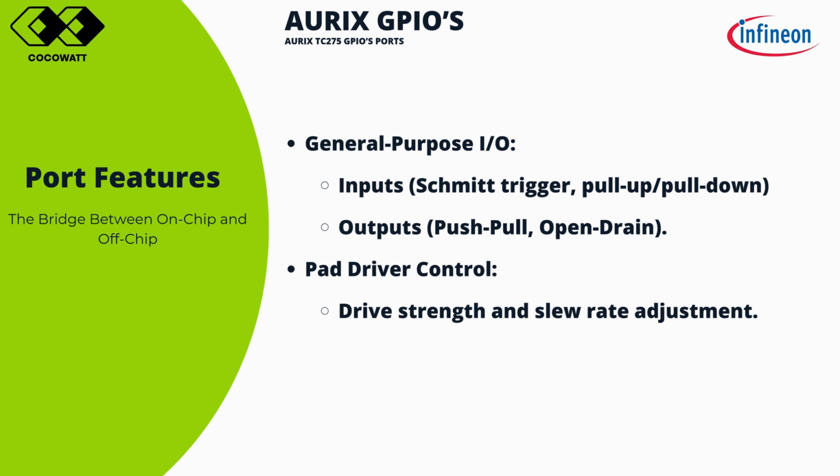Pull-up and pull-down resistors ensure a known logic level when the pin is not connected. High impedance state leaves the pin in an open circuit state, preventing unwanted power consumption.